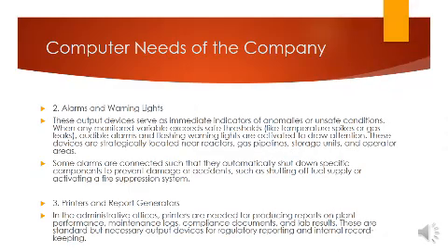We also have alarms and warning lights. These alarms help indicate whether there are anomalies or unsafe conditions around the site. For example, if there are leakages around the site, after the gas sensor senses these dangers, the alarm triggers and sends out a loud siren which tells all the personnel around the plant to evacuate the building. And we have printers and report generators which are used to generate lab reports and maintenance logs to check on permission.